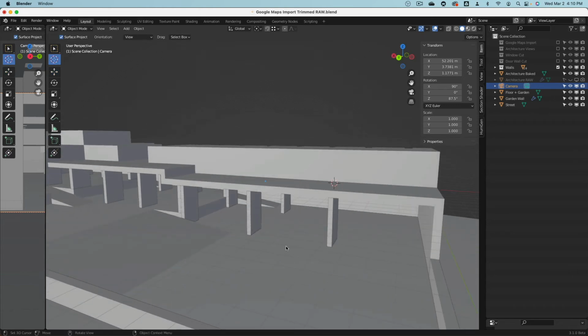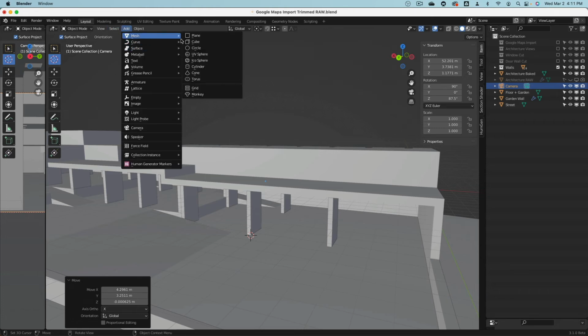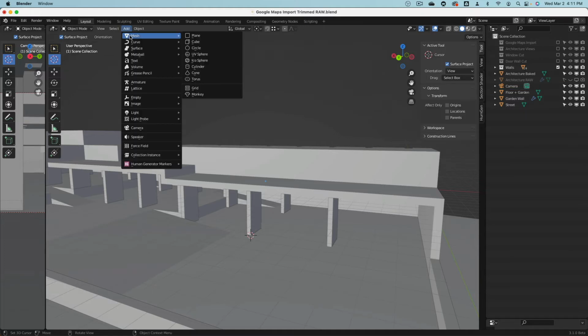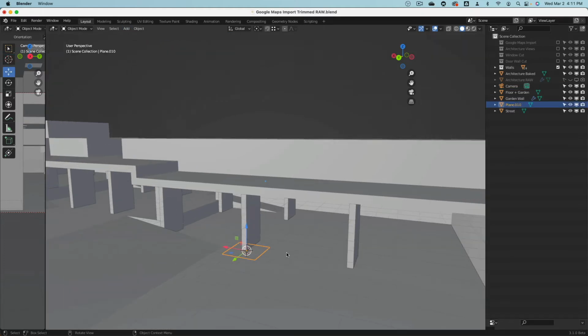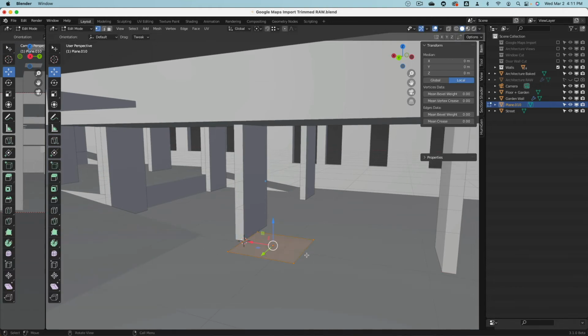So this 3D cursor, hold control. I left mouse button click drag and hold control, and then there it is. And then at that position, hold on, escape, add me a plane. Now this plane I'll move to here, I'll move to there.